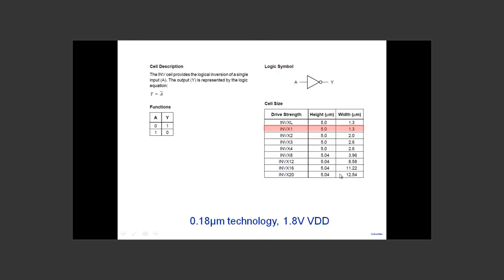This is a special cell which is a specially designed low power cell here. So that's something different. So ignore this for a moment. Just look at X1, X2, X3, X4. So what the manufacturer is basically doing, basic inverter is there, and the size of NMOS and PMOS are being basically doubled. Double, triple, 4 times, 8 times, and things like that. All right, so that's how the inverter is being designed.